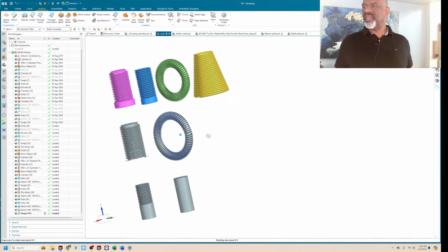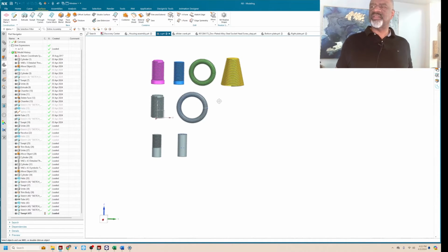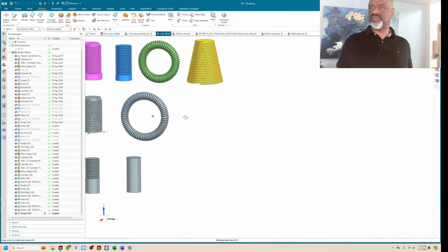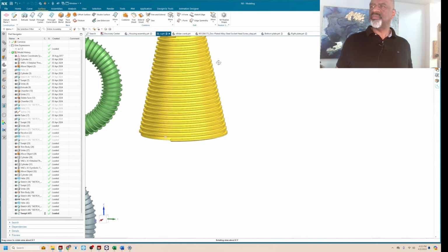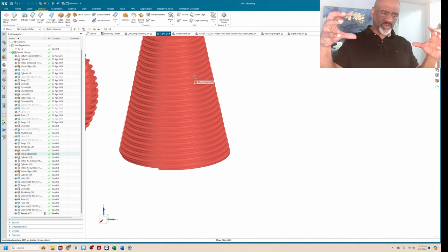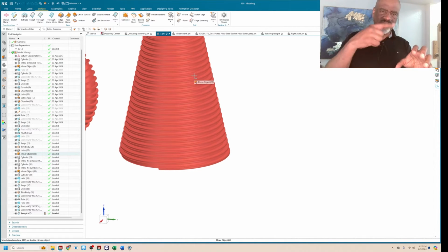Okay, the very next thing is a helix on a conical shape. There are threads that are on certain conical shapes. If you're in the oil well industry, you know that the different tubes that come together when you're digging a well, the end of those tubes have a helical thread, and that way when they thread them together, they don't have to turn them as much, because you go down, you engage those threads on this cone, and then you only have to turn it like 1 turn instead of the maybe 10 turns that you would have to if it were a straight thread.